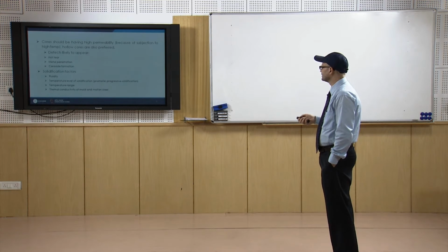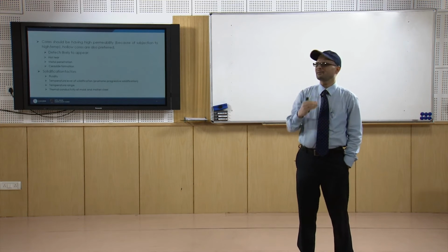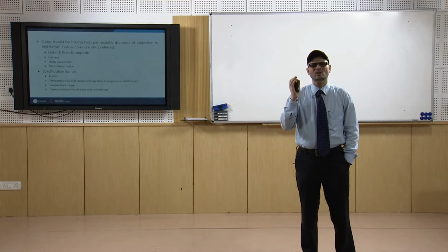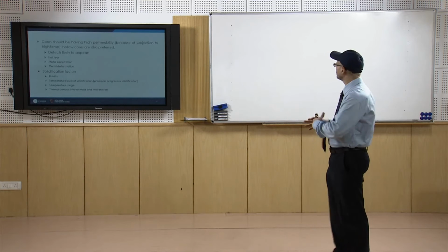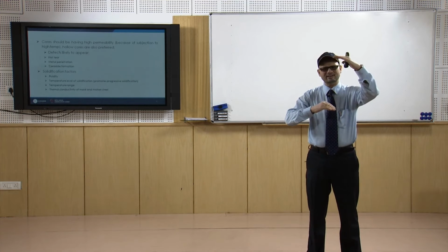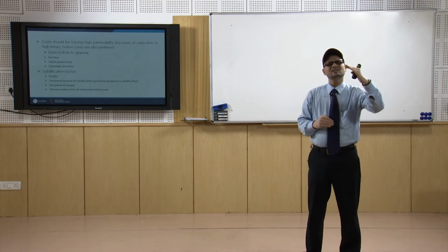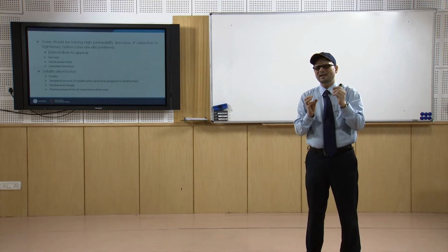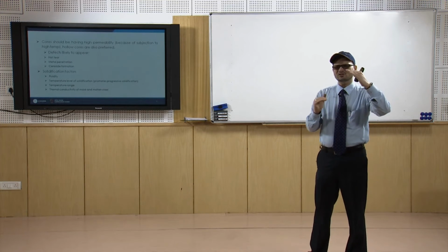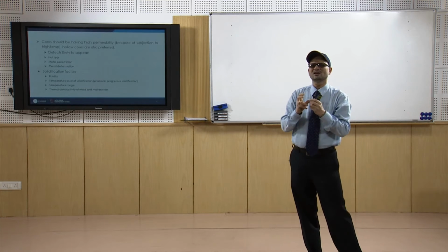As we know, since the freezing range is high, what happens towards the end, once we go through the liquidus-solidus range, the liquid plus solid range, slowly as the temperature falls, the liquid portion will go on decreasing and the solid portion will go on increasing. So towards the solidus line,